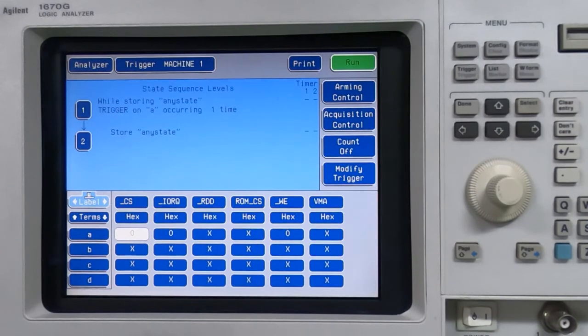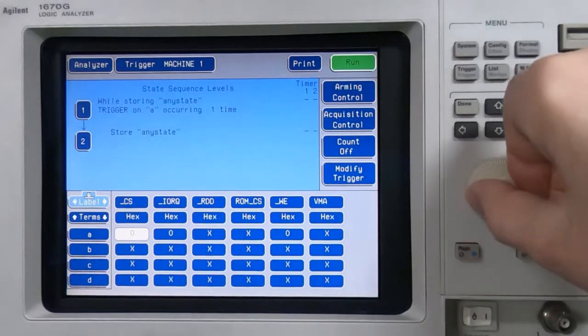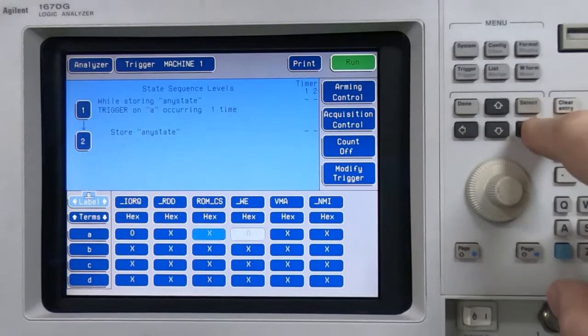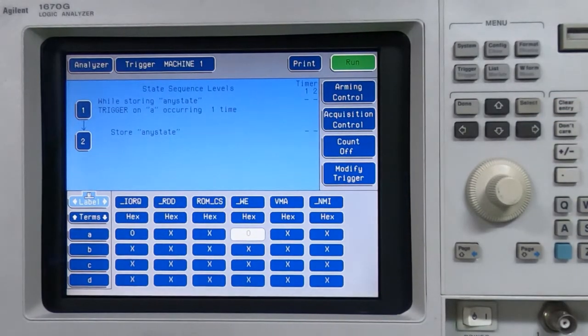In other words, when the floppy drive controller is selected, that line goes low. It's controlled through what I believe is an IORQ, so in-out request from the Z80. So again, we can monitor that for an active low. And then finally, if we look at the write enable line, so this combination means that we should be able to trap a write to the status register on the floppy drive controller chip.